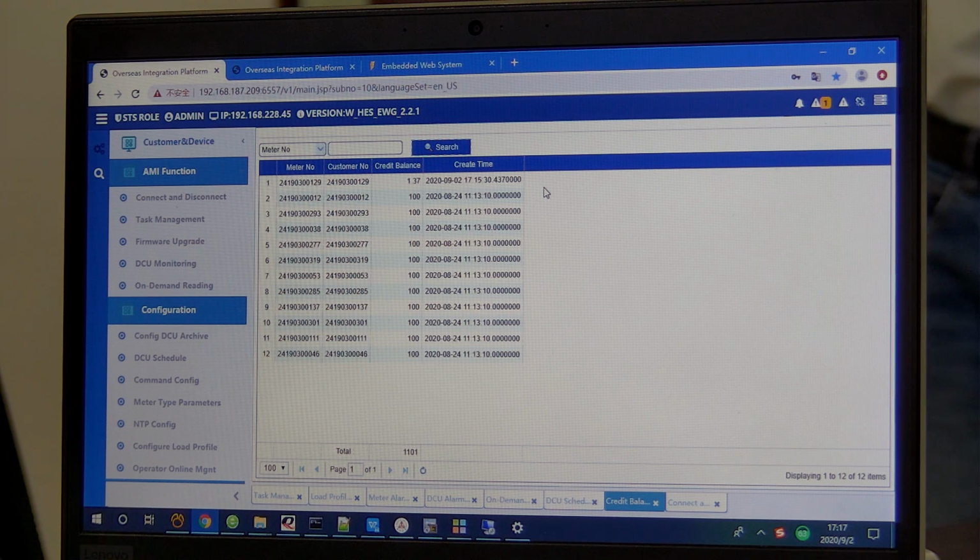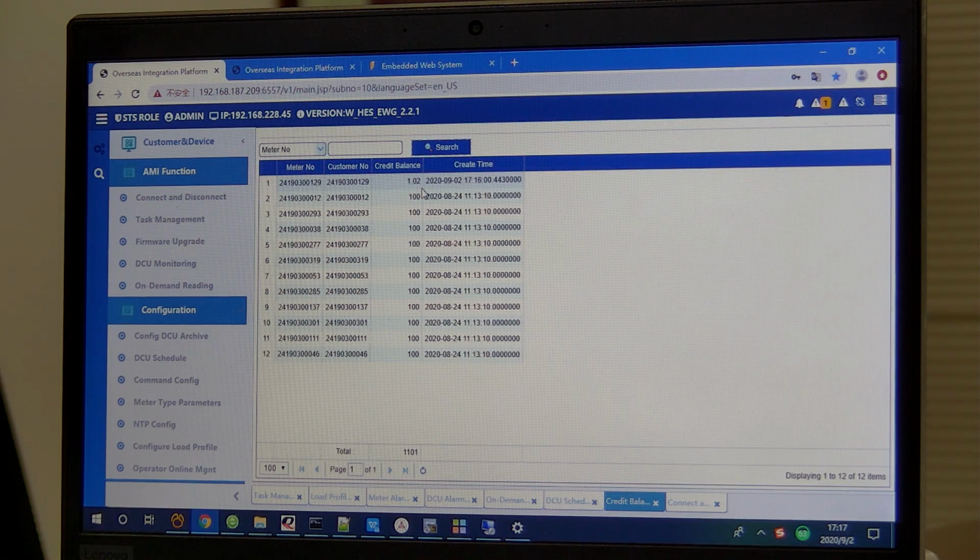Okay, Mr. Ma, I kindly ask you to refresh the screen. Now it is 1 monetary unit, so we have consumed almost half of our credit. The main meter will remain on 2 RMB because it cannot measure the consumption. The load is connected before the meter, we bypass the meter. But the system itself can measure this and can react. It does not matter what the customer's main meter is saying. We can measure and we can detect the illegal connection of load.